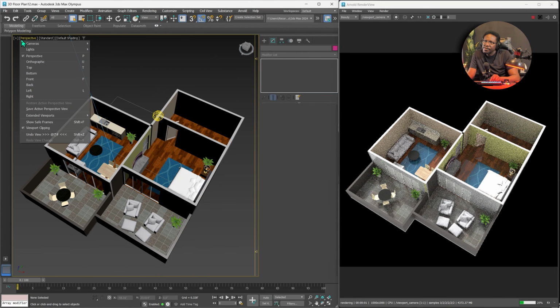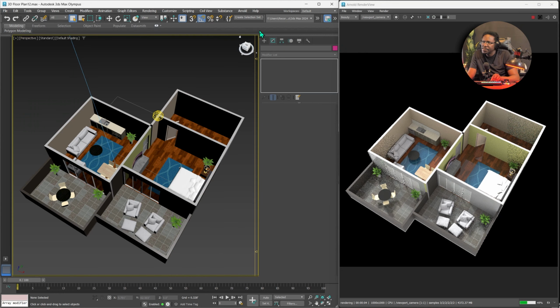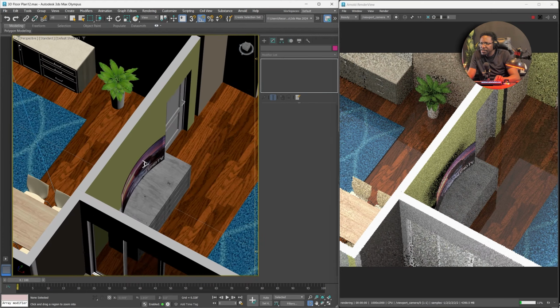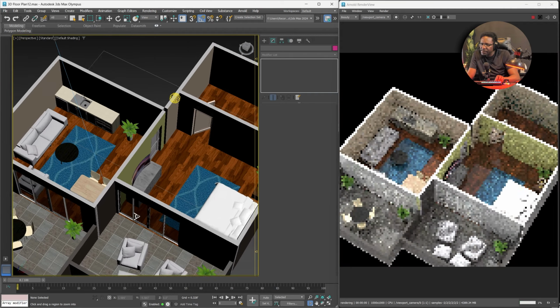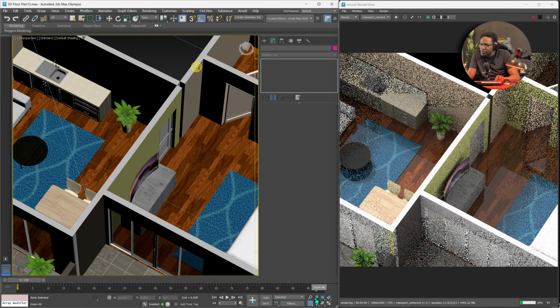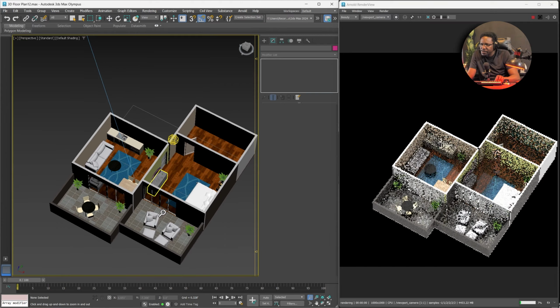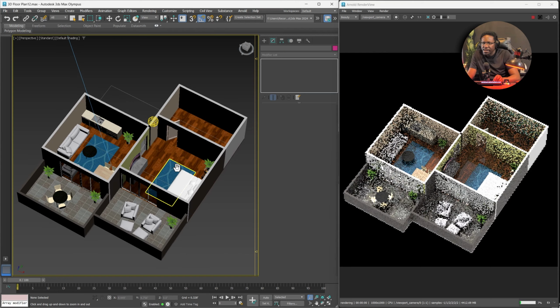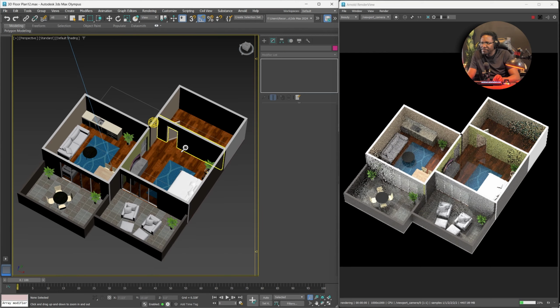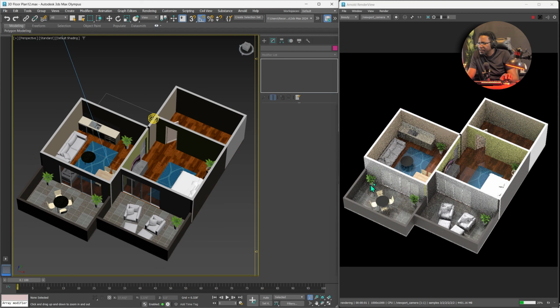And we're also going to go here and we're going to turn on save frame so we get a preview of the rendered view. Then we are going to use the field of view settings to zoom in and then to make our view less skewed. So we're going to use the field of view to zoom in and then the zoom tool to zoom out. So then we get more of an orthographic kind of view, right? And now that we have an orthographic view, let's angle it a little bit so we can see inside and the whole floor plan nicely.